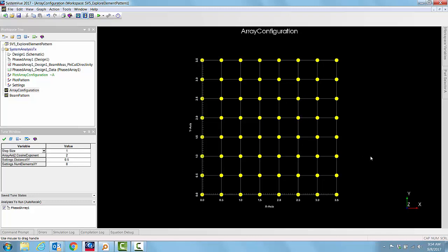So we have an impedance that depends on the nature of the coupling from other elements coming into this antenna element. If we have that kind of active reflection coefficient matrix, then we can easily account for the more realistic behavior of the antenna.